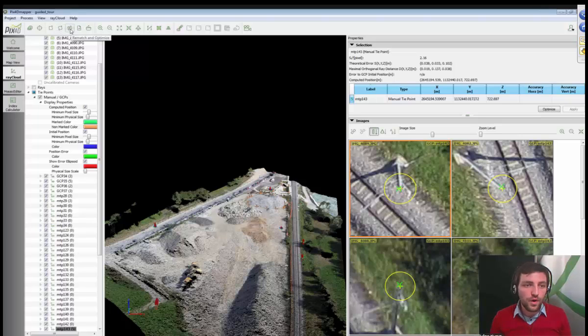If you are in a situation where some images were really not at the right location for some reason, that they were really bad, but then you added some manual type points, if the calibration was really poorly performing, then reoptimizing will not be enough. In that case, you will want to hit Rematch and Optimize, which will take more time than simply Optimize, but which will be able to even realign extremely badly calibrated images.